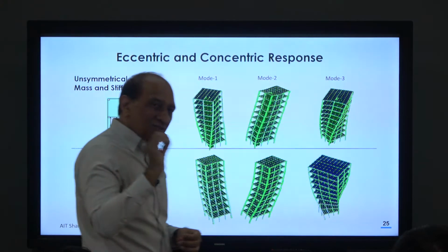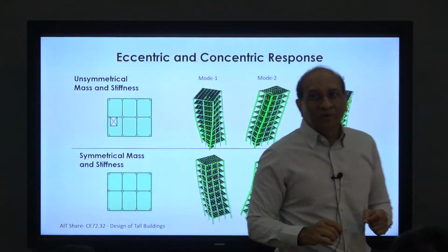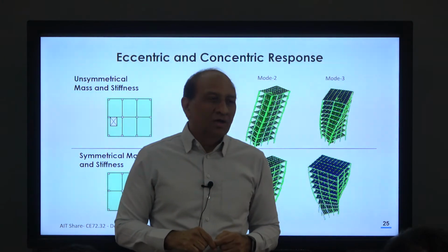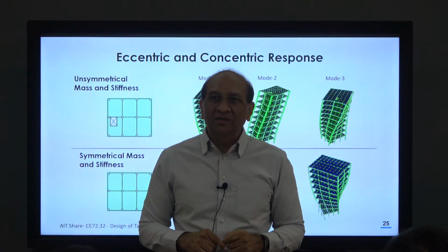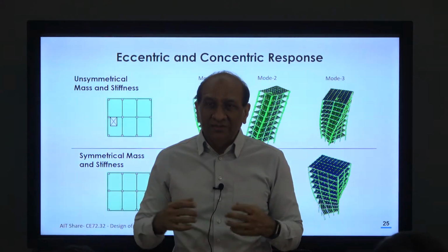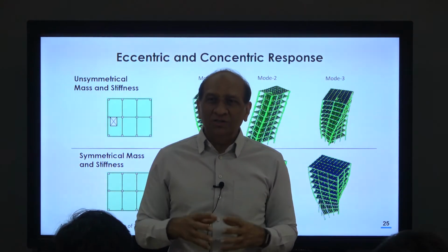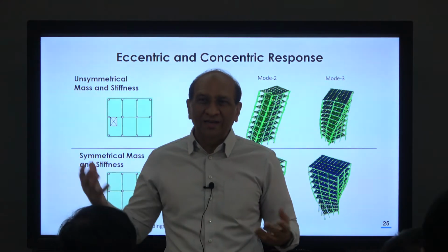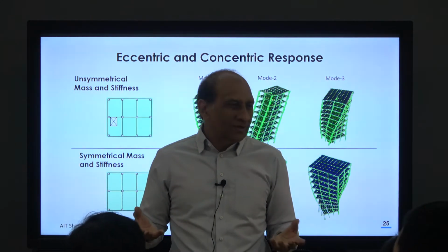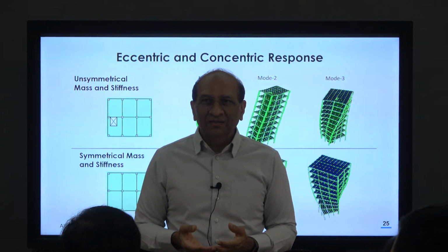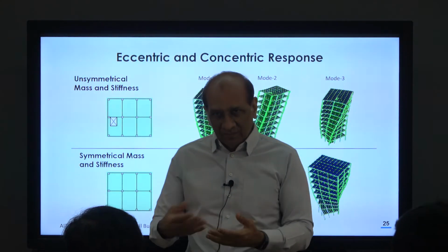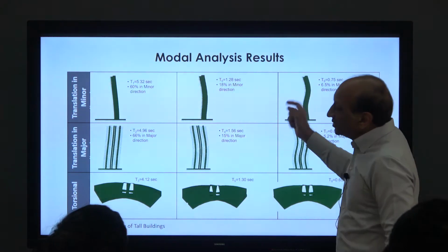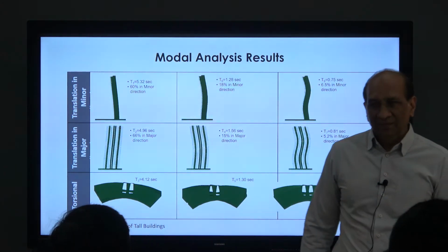So you have to understand, you have to know the rules and also know when to break them. So this is one instance where you can break the rule of the first mode being torsion, right? And I also understood this much later. I also used to worry, what happened, why is this building twisting? You know, it's so symmetrical. Then we looked into that and understood, oh, that's what is happening. Okay, this is very important. This is a very important slide.